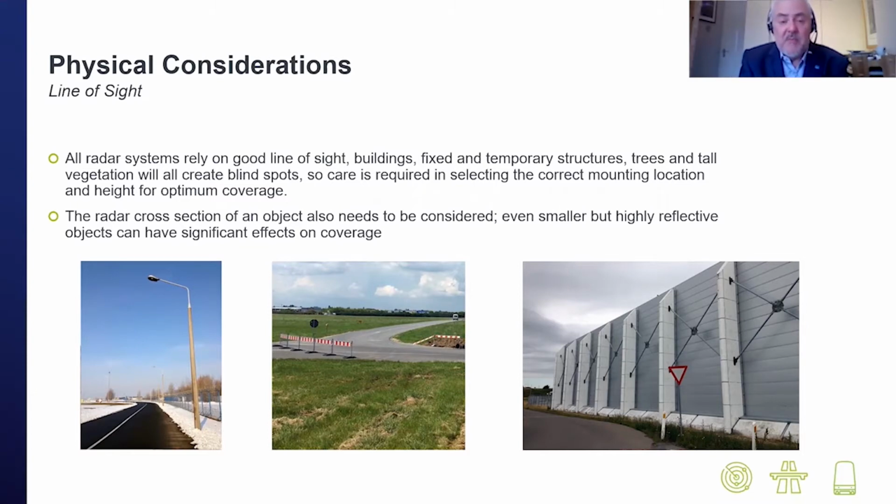Relatively small metal targets, such as posts, particularly very close to the radar, can create significant reflections, which may be powerful enough to mask any intruders close by. In this instance, this is where radars which can analyze the clutter more effectively will perform much better, particularly if it's a very cluttered environment. So going back to my previous point, really, the resolution size or bin size is very important.